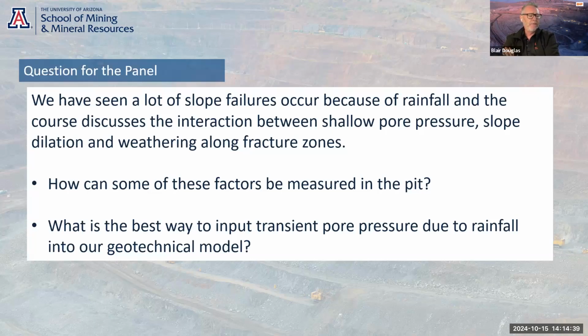There's a bit of back analysis as well that needs to be done here. And on that RU, yeah, Jeff, that's really the only option we've got, but it's a bit of an ugly parameter to use, the RU. It's really not that applicable in most cases where you have a little bit of complexity in the hydrogeology, and you're really just playing with a bit of a fudge factor between 0 and 1. So even though RU can be used, you still have to relate that back to some sort of hydrostatic condition. Yeah, but by varying it, it can actually pinpoint where the susceptible parts of the slope are if you don't already know them. So I think that's the way we would use it.